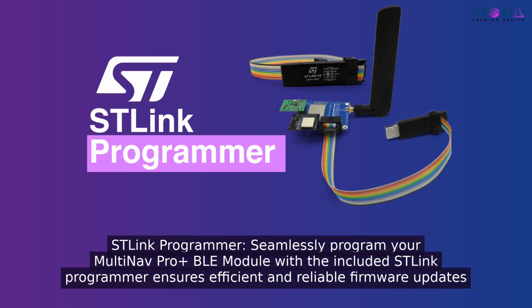This is the integrated ST-Link programmer. It connects directly to the Multinav Pro Plus BLE module through the flat ribbon interface. No adapters, no improvised wiring, no opportunity for a loose connection to introduce resistance into the SWD line. The programmer draws its power from the same supercapacitor bank as the target device. Ground reference for the programmer and target are identical. This eliminates the ground loop failure mode entirely before the first flash command is issued.